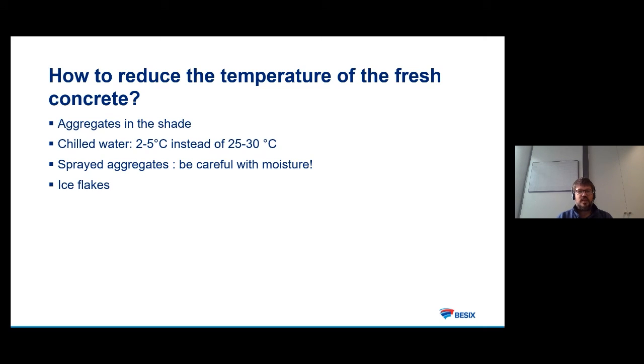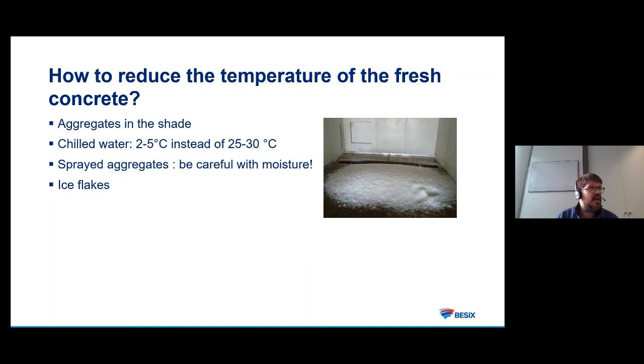Ice flakes. In the Middle East, we are using quite a lot. We are putting ice flakes into the concrete. What we do is we replace a part of the water by ice flakes. The ice flakes, something like this. So it's really crushed ice. For those who are not able to imagine, it's exactly the same ice that you put in your mojito.